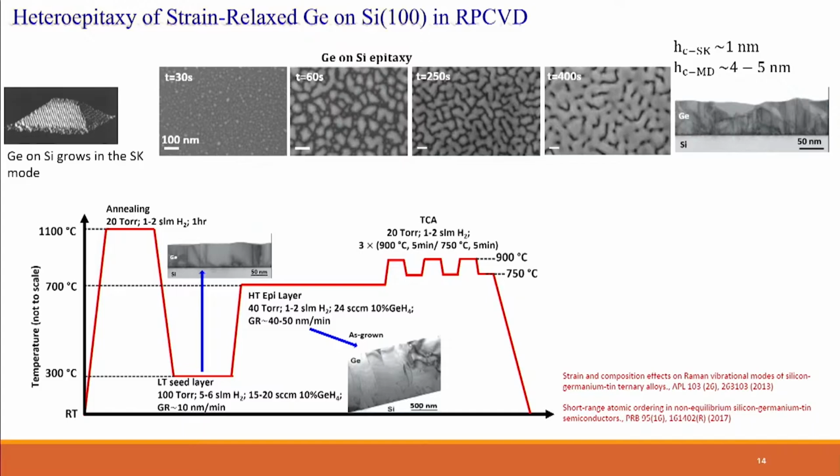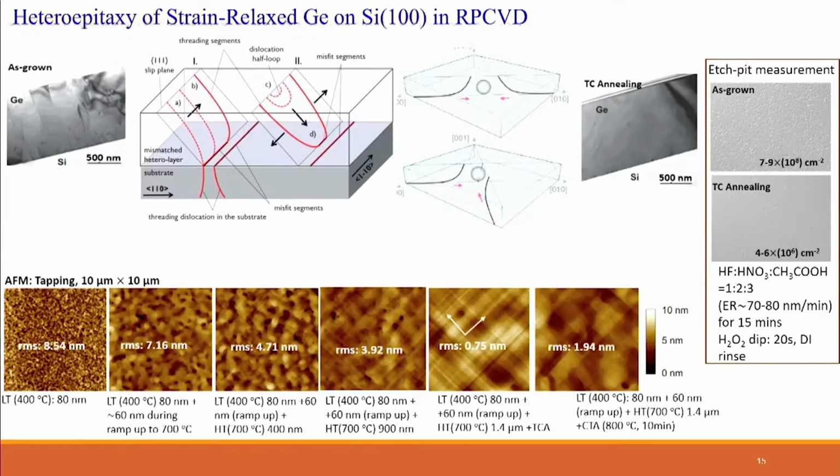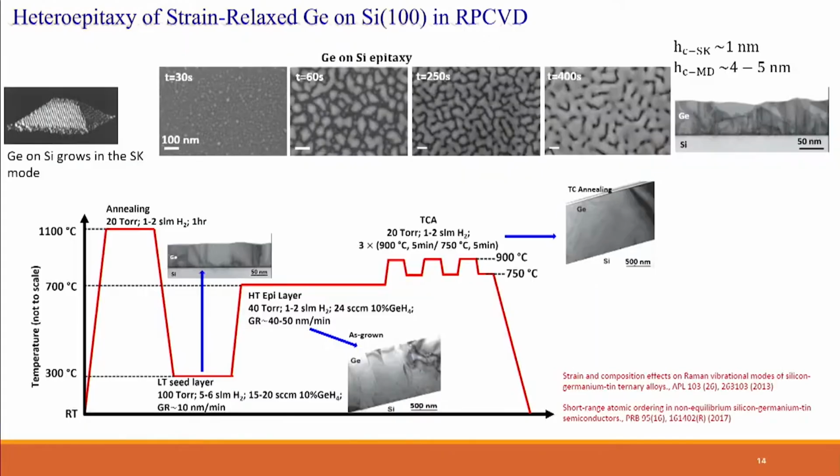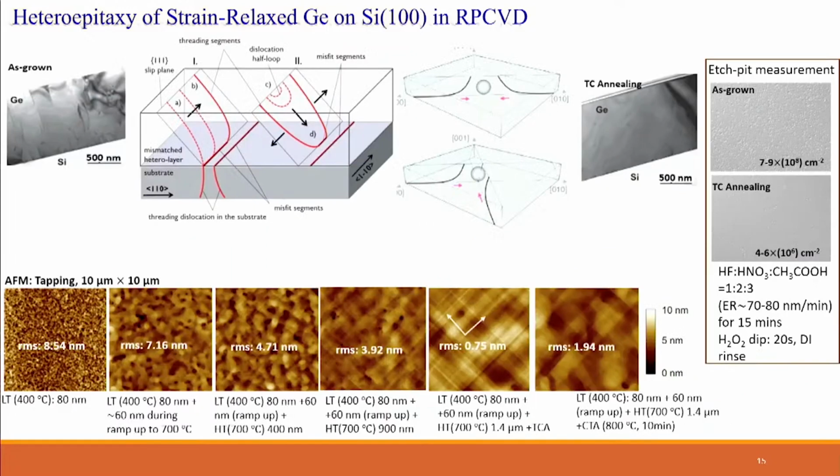Finally, we heal the crystal using cyclic annealing, and I'll tell you why cyclic annealing is necessary. It gets rid of these dislocations that were formed. Now, I told you about mixed dislocations. Remember, if it is a pure edge dislocation, a Lomer dislocation, with this as the interface, its glide plane and slip plane is this interface. It never propagates upward. It releases the strain and remains in the interface plane. Mixed dislocations, because they have a screw nature, nucleate differently. They nucleate on a growth front as half loops. You can see these loops there.